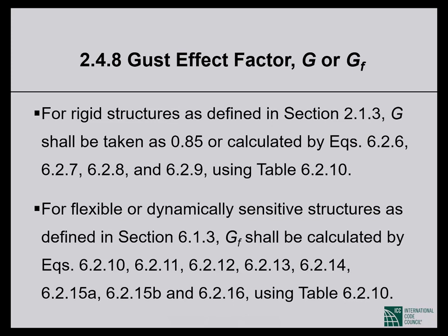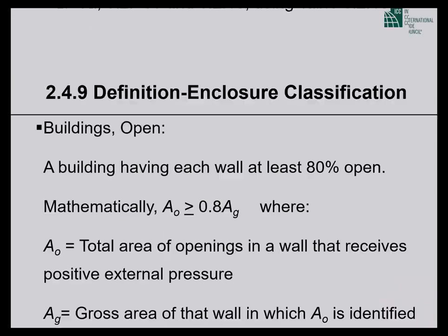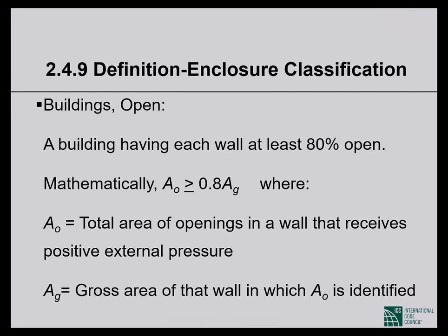I'm not saying that you never calculate more than 1, you do. But ASCE 7 also tells you if your G is very large, definitely exceeding 2, in the range of 3 or 4, you should not apply the all heights method. Then you need to do sophisticated dynamic analysis, which no one knows how to do, or you have to go to wind tunnel testing. Okay, so anyway, the calculation of gust effect factor for flexible buildings is a project in itself, unless you have spreadsheets and so forth set up in your design office.